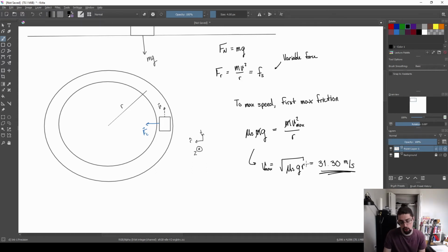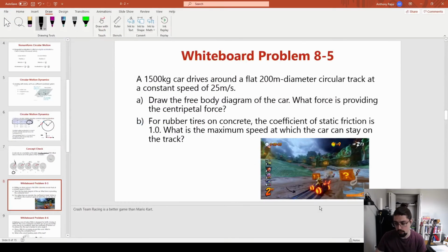Static friction and not kinetic friction because the tires relative to the road are not moving, right? It's kind of the difference if we go back, I realize this is a cartoon picture, but it's really the difference of if your tires are sticking to the road, then what really goes on there is that the rubber that is in contact with the road itself is not moving, right? It's supposed to bite into the road and remain there. The car propels forward because that bite doesn't slide. And instead, it starts to lift up, and the forward rubber kind of comes down to layer onto that and then grabs as well and bites.